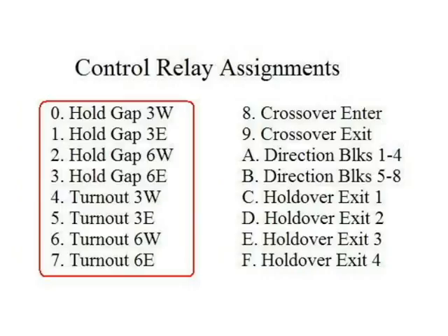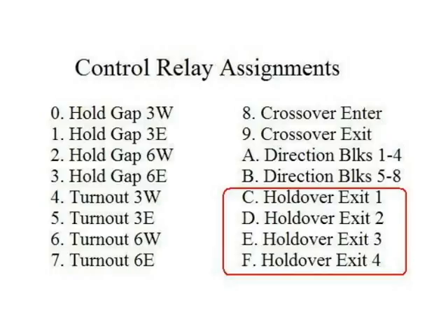Now, to dispatch the trains from down here, we also need relays, and right now only 4 tracks are operative, and they take up 4 more relays, and that ends up being the entire 16 relays. Now, what I'm going to do down here, by the way, is to multiplex them a little bit.